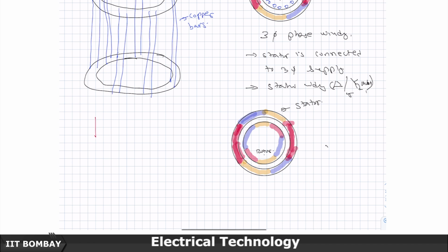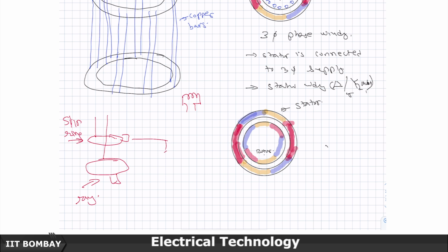So, A phase winding will come with one slip, let us say like this, and another terminal of it will come. So, a winding has to have two terminals. So, this will come on one ring, this will come on another ring, and these are called slip rings, because to connect it to anything in the stationary outside world, let us say you want to connect a resistor here which is placed in one particular location, then these brushes will connect to the slip ring. This would be carbon brushes or so, and this could be copper, for example, ring.